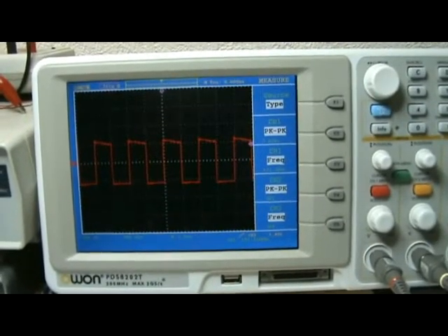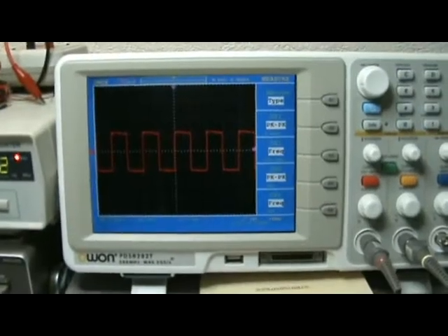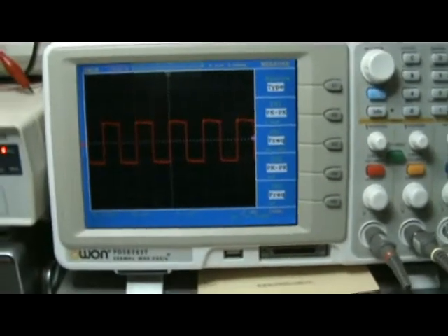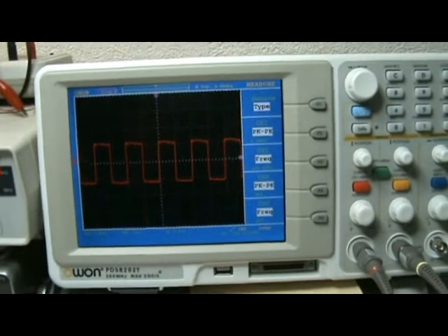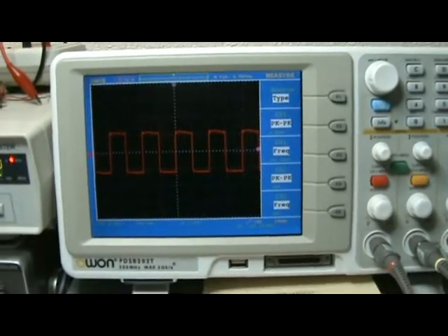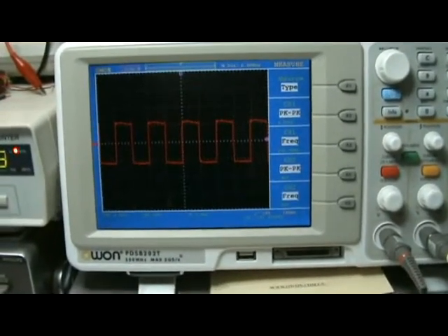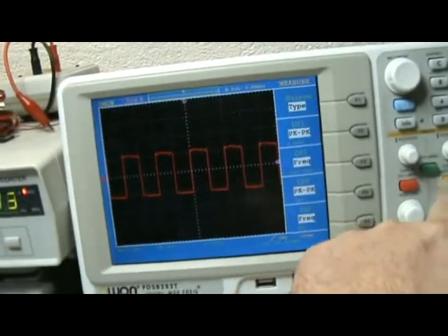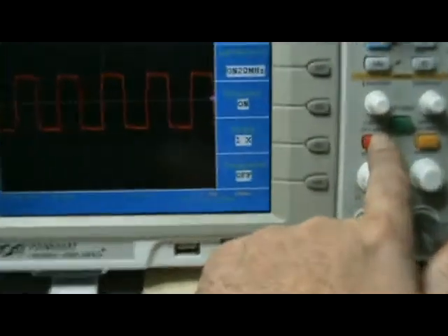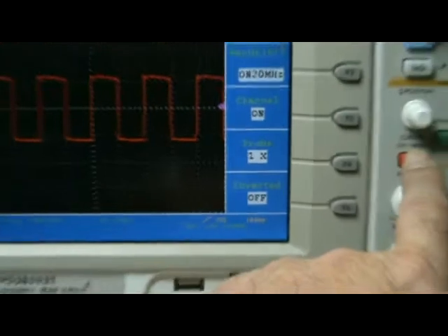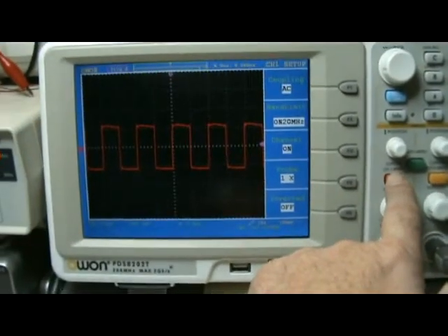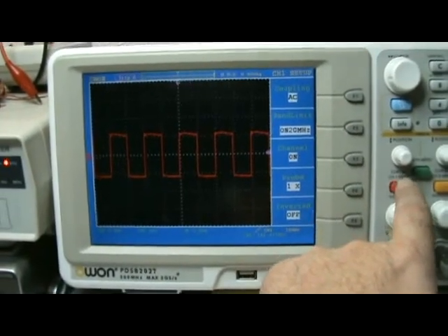Okay, I'm going to change my probe to 1 time and see what's different. Back again, still on 10 ohm resistor, still on square wave. I have to adjust the scope shot a little bit. I'm now at probe 1 time. I also switched the switch on the probe itself to 1 time.